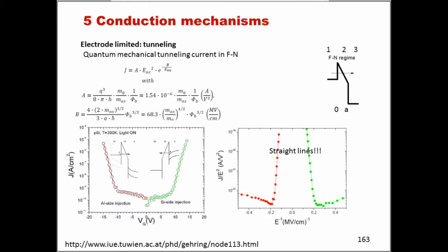Now, in the case of the Fowler-Nordheim tunneling, we can arrange the equation a little bit better just to understand more clearly where the important terms are. So we can write the equation that relates J and the electric field in this way here. J is A times the electric field squared times an exponential that depends effectively on 1 over Eox.